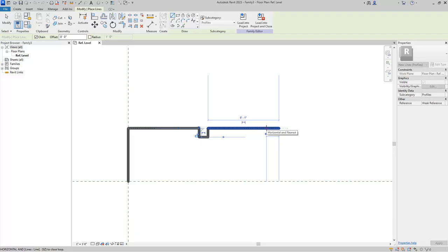And at this point, I'm going to stop drawing the profile. We now need to define an angle. The angle is going to be best formed by utilising just geometry, just snapping to endpoints. So to stop drawing, we'll press Escape. Of course, we're still in the Line tool, so we can now start to redraw on the bottom point here.